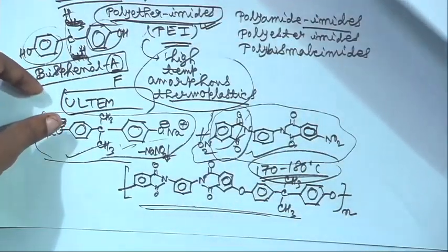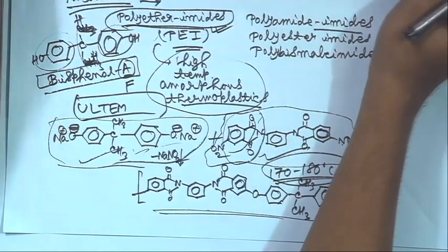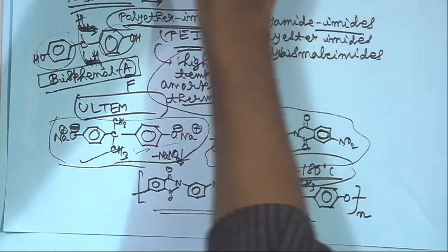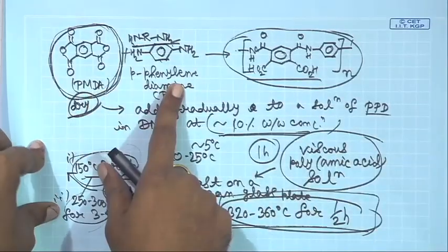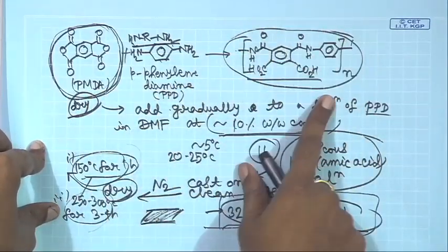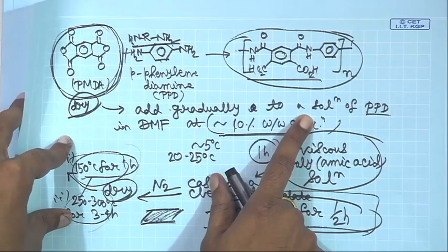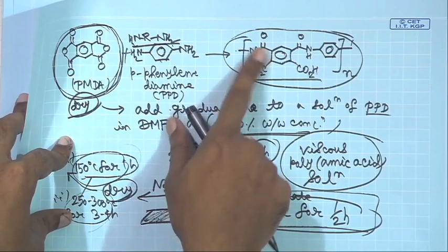One thing that you have to keep in mind here, when you are going to the second stage of the polyimide preparation, in the typical polyimide preparation process, here you are going through polyamic acid synthesis. So, when you heat this up and you get your polyimide, you are basically producing water, because this is cyclizing.